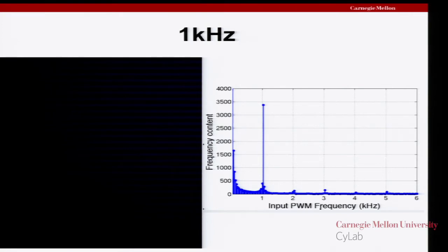If you look at the frequency domain of the image, because of the rolling shutter effect, the bars are always perfectly horizontal, so you basically only need to take the central stripe of your 2D FFT. So if you plot that, what you see, of course, is a big peak around 1 kilohertz, because we're broadcasting a 1 kilohertz sine wave.